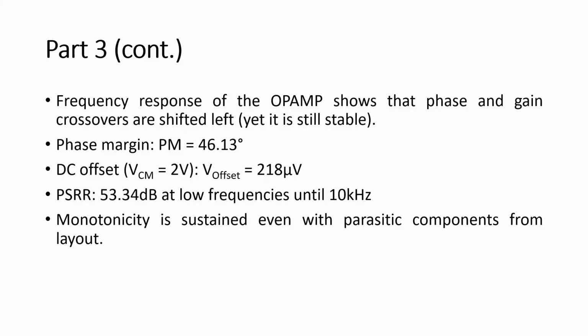Then I performed the final simulations with the extracted layouts. The phase margin is at 46 degrees, the DC offset is at 218 microvolts, and the power supply rejection ratio is at 53 decibels, and the monotonicity is still sustained even with parasitic components coming from the layout.